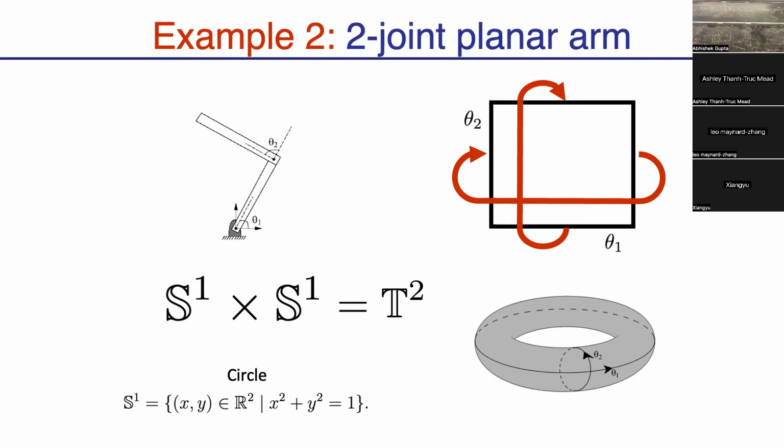He's talking to me about inverse kinematics, right? If you've heard about inverse kinematics, it basically says, given an end effector point of the robot, what is theta 1 and theta 2? And forward kinematics says, given theta 1 and theta 2, where is the point of the robot? Because it's a rigid body and it's fully defined by theta 1 and theta 2, you can think of forward kinematics as something that connects theta 1 and theta 2 to points in the 3D space or the 2D space. And inverse kinematics connects points in the 2D space back to configuration space. So if you ever see those words in any papers, that's what they refer to.